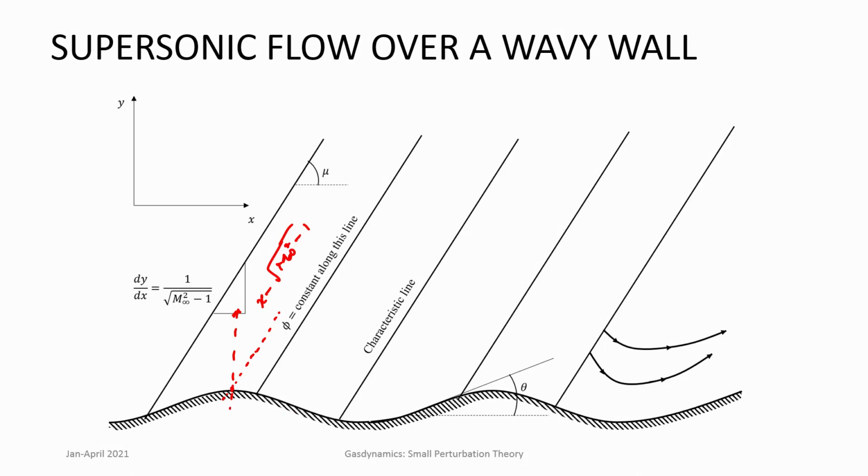So, they are getting displaced or stretched by a certain amount along these characteristic lines. As a consequence of these effects, you can see that it is written over here the way the streamlines behave. The consequence is that if pressure is integrated over the wall, then you always get a finite drag for this particular solution.